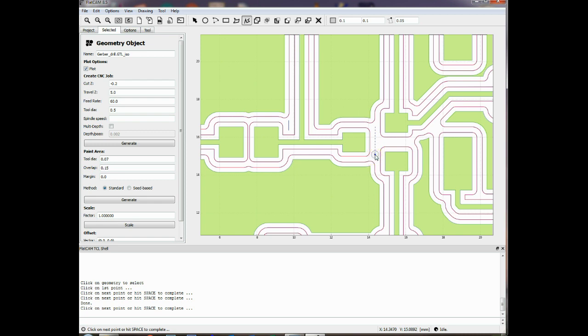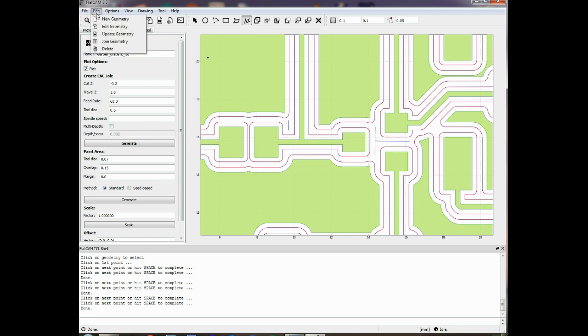So it's just a quick example. For example, in between this transistor I had some unfortunate little filaments. So this geometry I've added in here is going to result in a tooling path, which means that the milling tool is going to mill out that unfortunate little bit of copper that's not required, and the same here and elsewhere. So once you've done that, again you go edit, update geometry. And now they're part of the geometry.